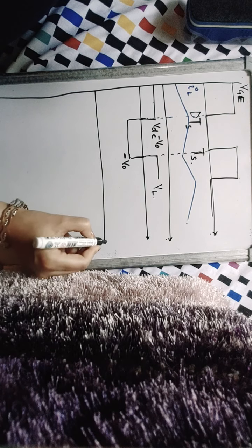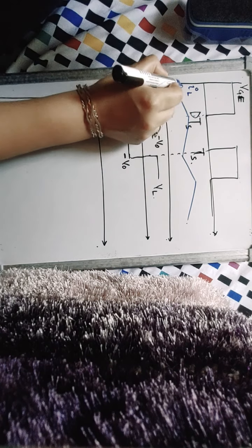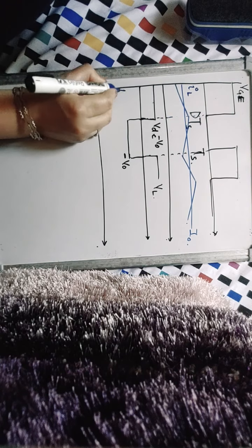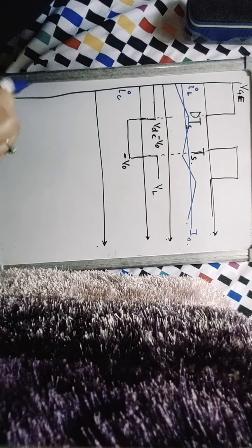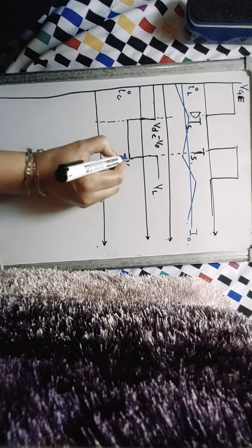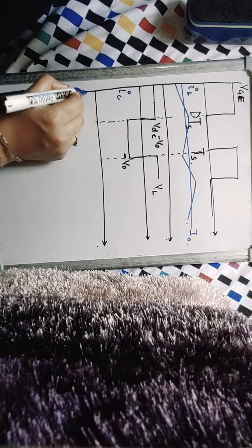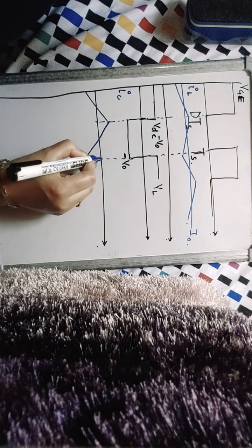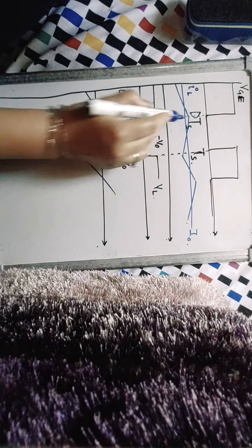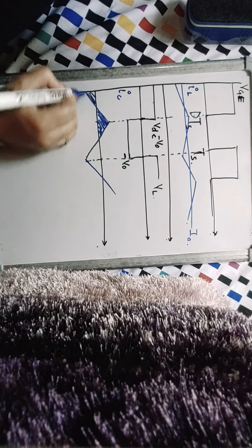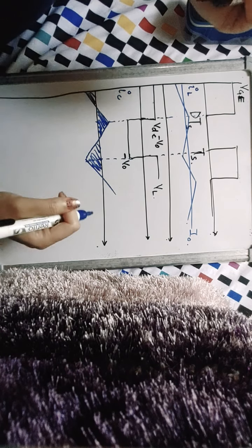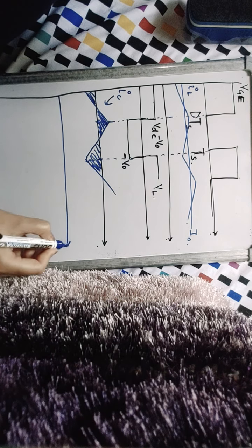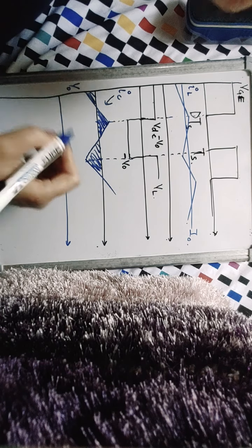You assume that your load current is almost constant and equal to the average of the inductor current. Then your capacitor current IC will be IL minus I naught, and it will look something like this. The same ripple. So the capacitor may be charging and discharging within each cycle multiple times. Now this is your capacitor current, which we have drawn before also. And from the capacitor current we can draw the load voltage or the capacitor voltage.